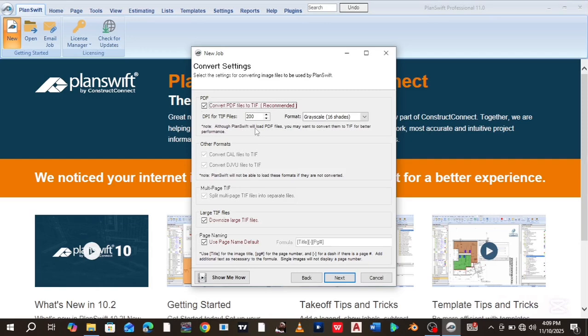However, if you are looking for precision, if you want your measurement to be very, very accurate, I will advise you use your AutoCAD file. Why do I say that? Because the AutoCAD file allows for snapping. If you are conversant with AutoCAD, AutoCAD has a feature called snapping, which allows you to have precision on corners.